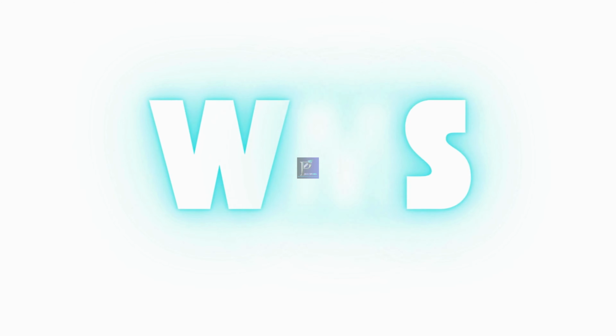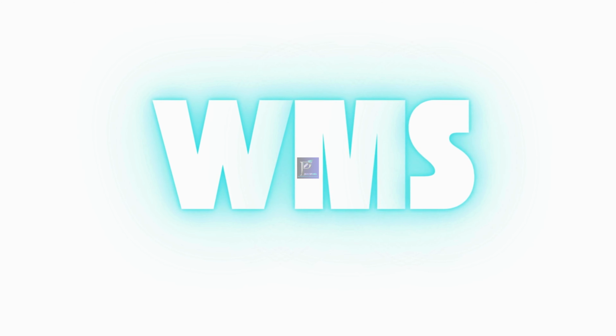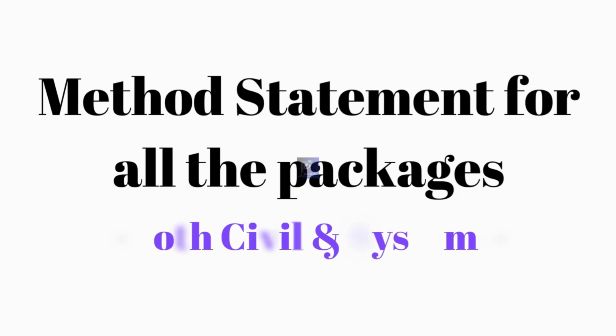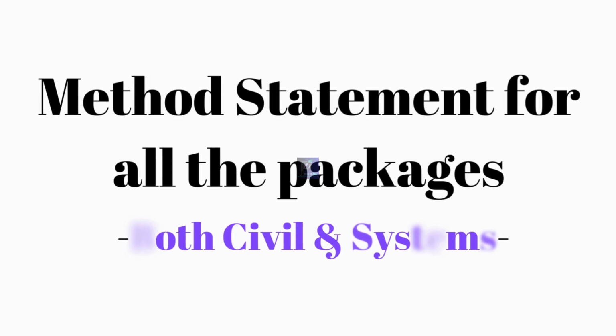Before we discuss this mantra, let me first outline a key construction document, the method statement. Generally known as the work method statement, or often referred to as method statement. As the name suggests, this document explains the method of execution for a specific task. It may be painting works, cabling works, earthworks, or concrete works. It contains all the relevant details related to a particular activity.